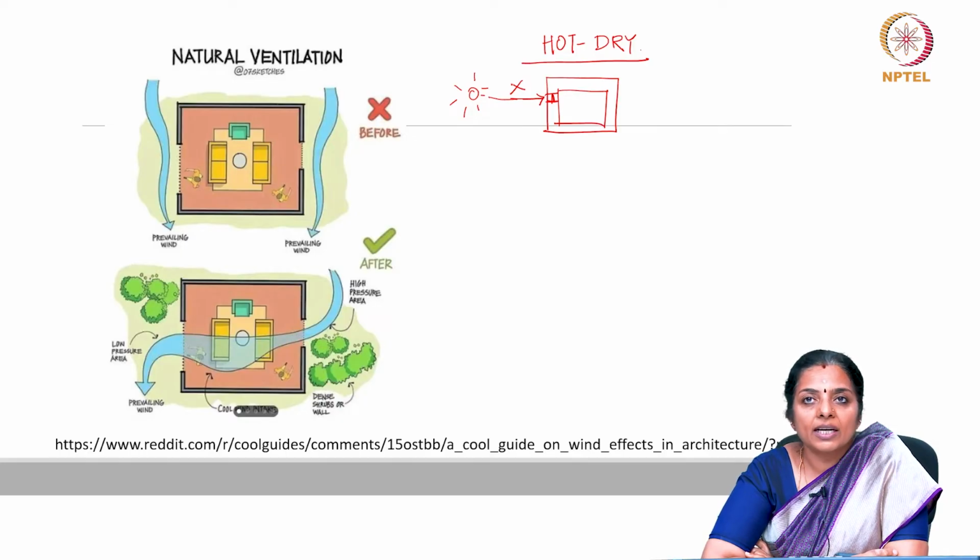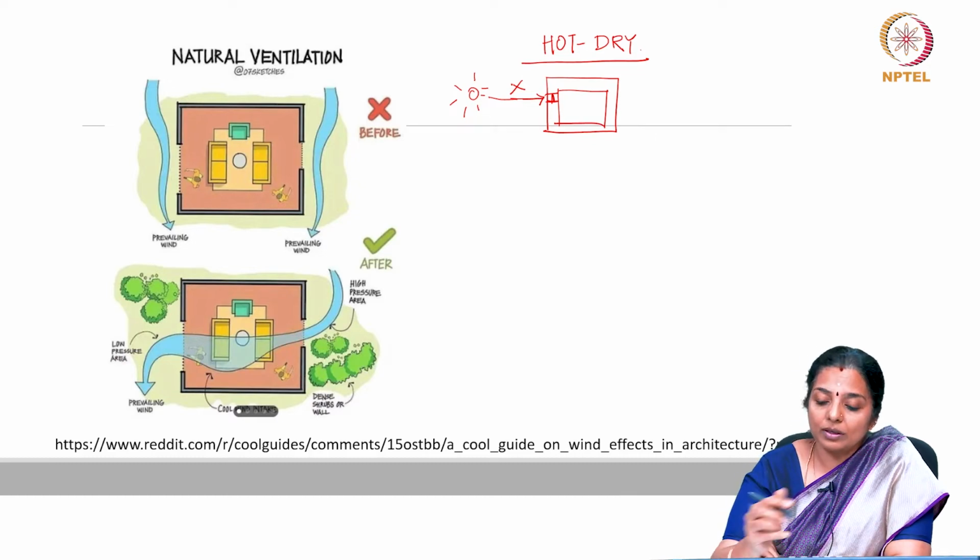Airflow need not be encouraged since daytime air is hot, in fact very hot. Due to low night temperatures, natural ventilation may be desirable at night. Window sizes, if increased for this purpose, must be efficiently shaded from radiative heat gain. High openings or ventilators would be effective as heat vents. How does that work?